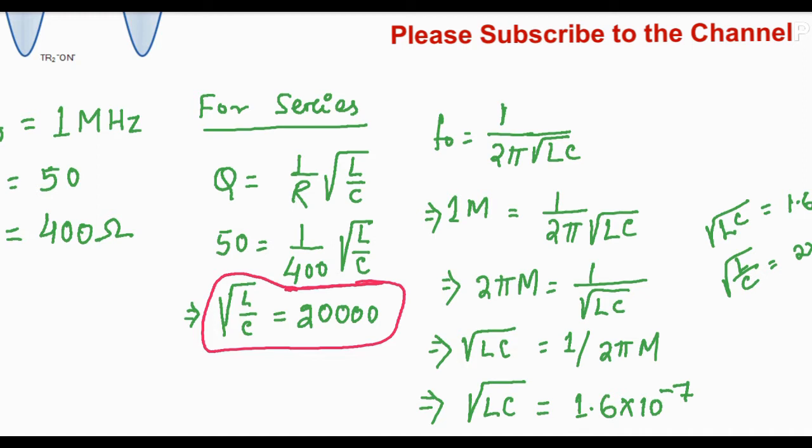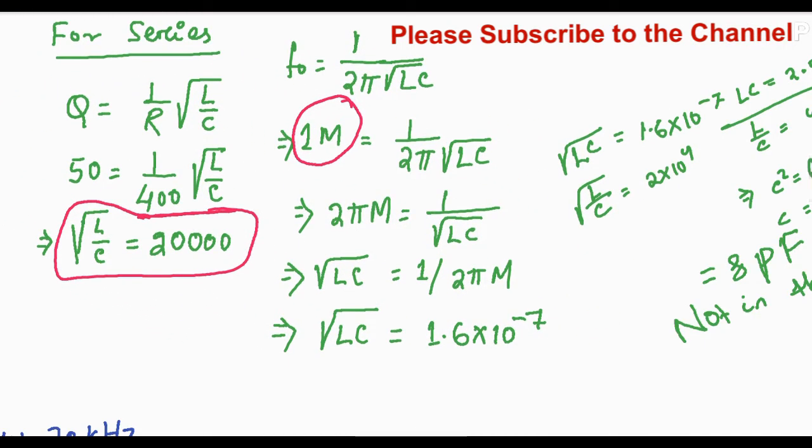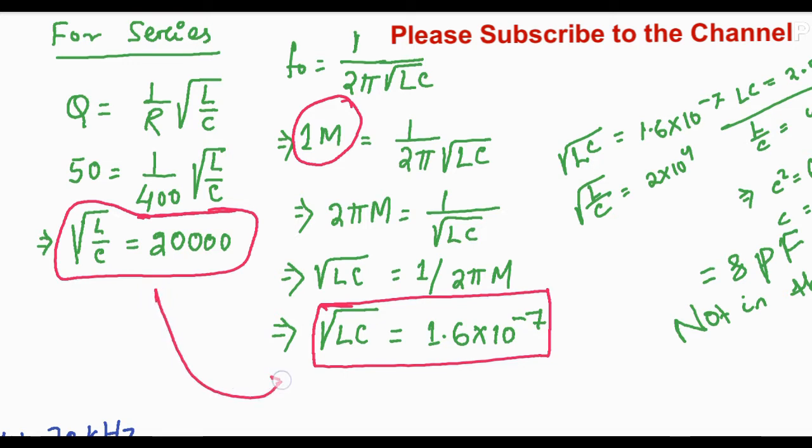So what will be the thing? Here it is given that F0, the resonant frequency, is 1 megahertz. If we solve this, we will get root over of LC as 1.6 into 10 to the power minus 7. So we have to solve these two things to find the value of C, because L is also not given.